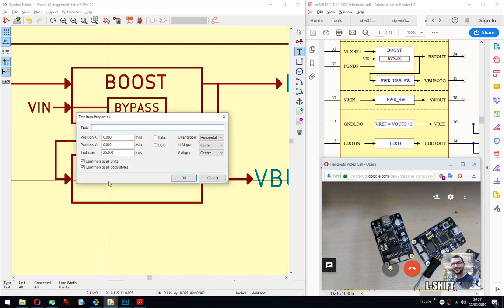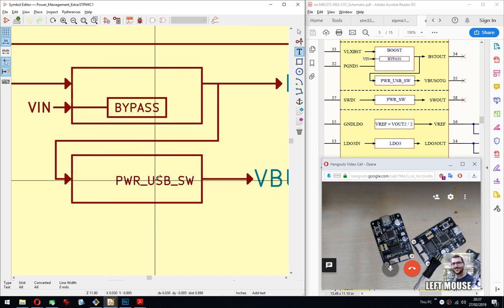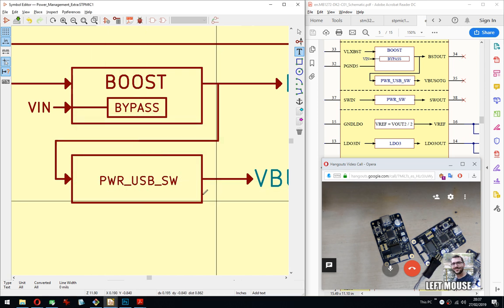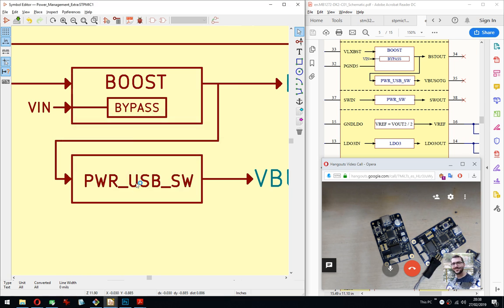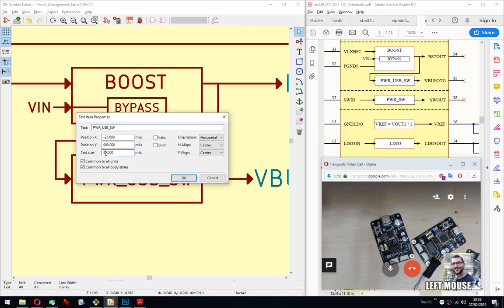But on the other hand, what you can do is grab firmware. There are UAV CAN capable bootloaders, and you can tell it to initialize the UAV CAN hardware before you boot, and check if there's a firmware update available, and if there is, pull it and run the new firmware. If there isn't, just run your regular firmware.